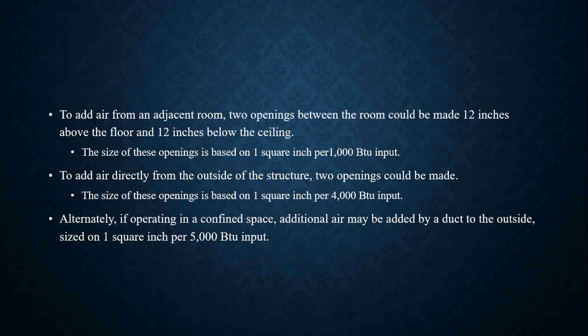Alternately, if operating in a confined space, additional air may be added by a duct to the outside, sized on 1 square inch per 5,000 BTUs of input.